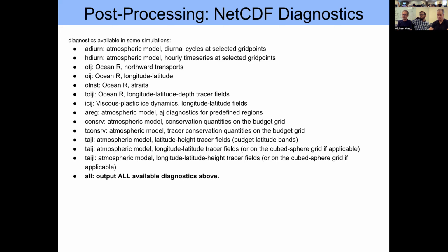So I would say that an extremely nice exercise for you to do, maybe after we're done today and have questions for tomorrow, is to follow the instructions that we gave you and run the model for just 1 hour, like the setup hour. You don't have to go beyond that. You will see the partial file that Mike mentioned, which is the output of the first time step. Just run scaleacc on that because it is an ACC file. You will get the output, and then take Panoply, ncview, or your favorite NetCDF viewer, explore the output a little bit, and come back with questions. You will have plenty.